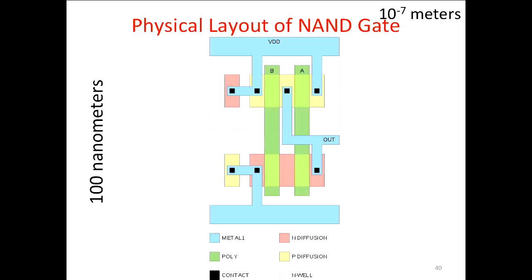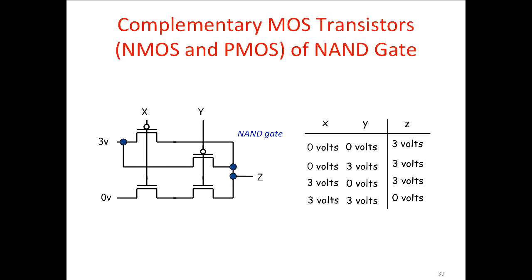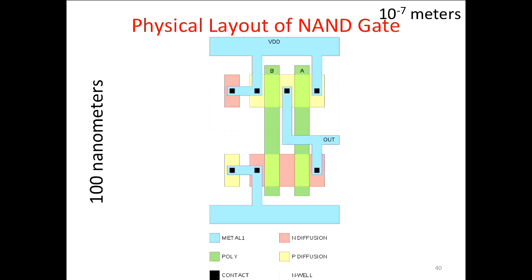These are the 2 pull-up transistors here. So VDD on one side, and this is their common node here, comes out. These are the 2 pull-down transistors. These are connected in series. So this is ground here, contacted here, and this is the output here, and this is the series connection. These are the 2 transistors. This stuff is the gate material, polysilicon.